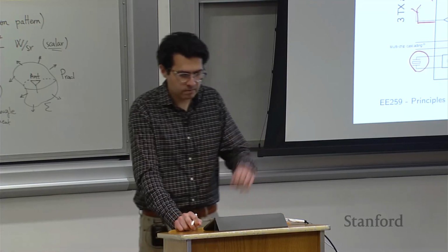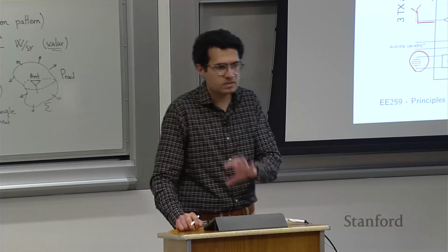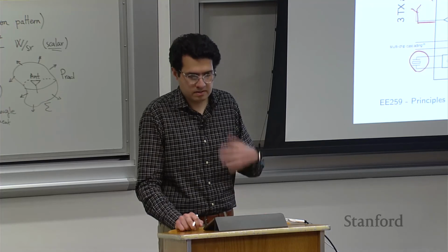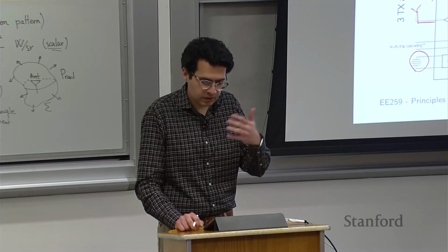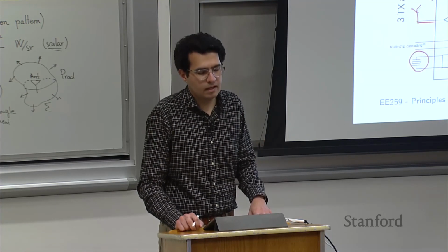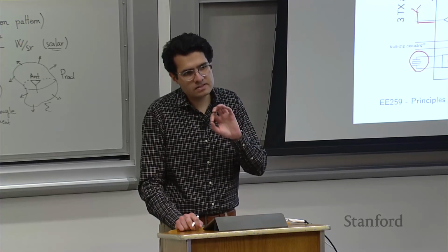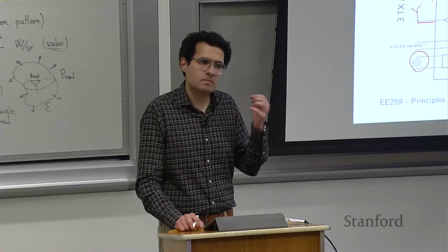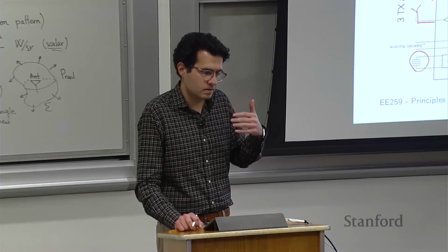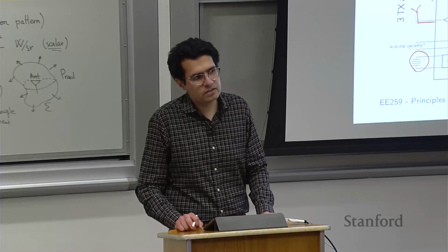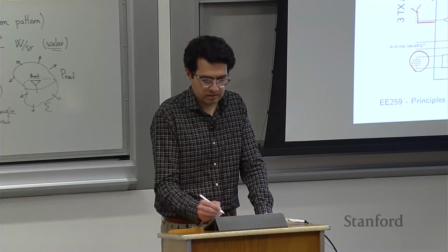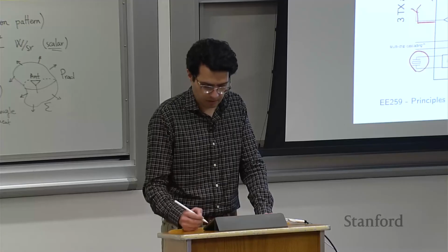And that's why FMCW is so dominant. PMCW is not at this maturity level mainly because of cost reasons. The requirements of PMCW systems, specifically the ADCs, need to be very high sampling rate, like gigasamples per second, which makes them expensive to make with the processes today. I'm sure in a few years that's going to change, and hopefully in 10, 15 years we can have chips like this that do PMCW also.